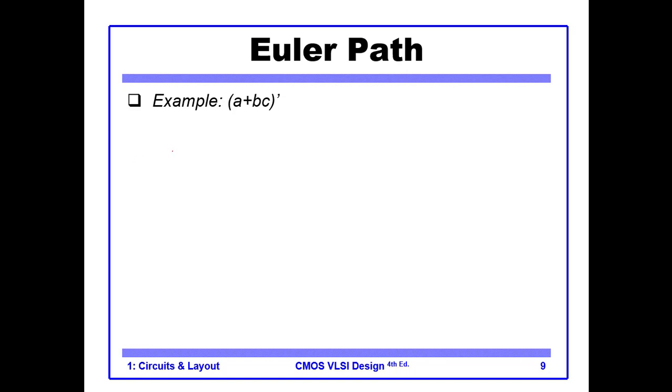So the example is like this. We have this (a plus b c) whole bar, and we want to implement this circuit. So first go to the static CMOS circuit, or let's say just CMOS circuit. Why do I have it in static here? Because later in the course we will study dynamic CMOS circuit, but for the moment let's say we want the CMOS circuit. Okay, so we have B and C, and B and C are ANDed, so they are in series. Okay, and then we have A, which is in parallel, and then we have this point which is connected to ground.